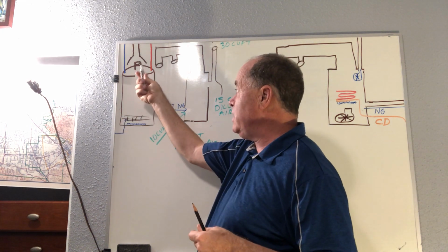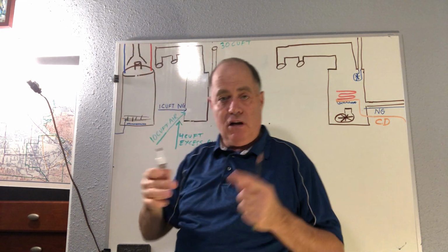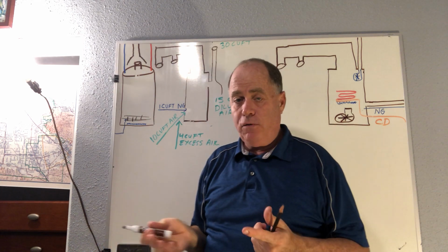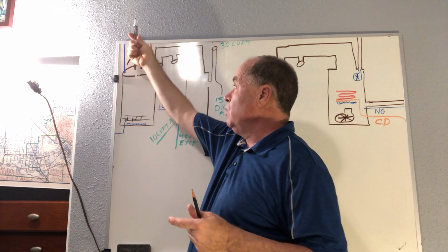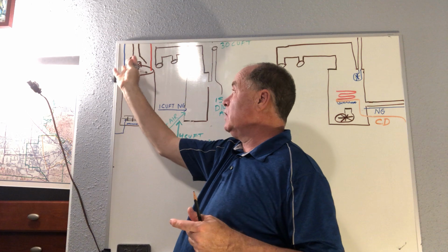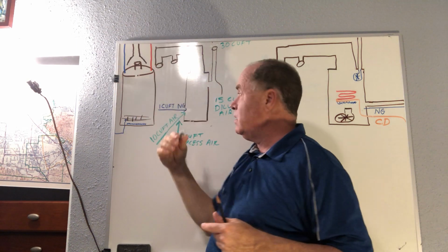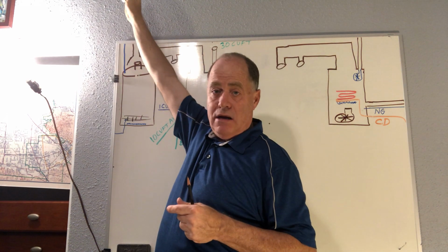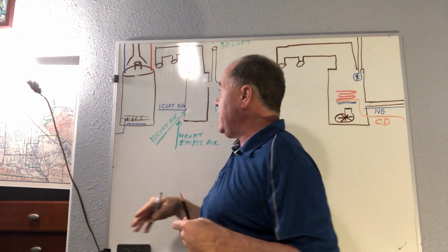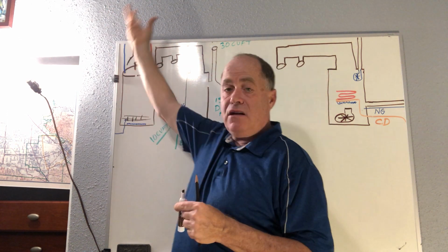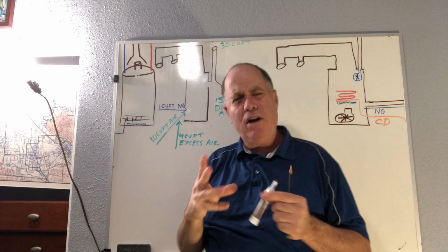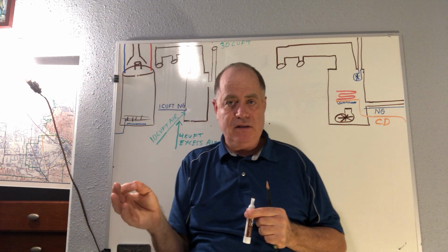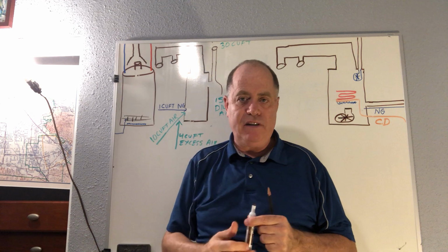Now the draft hood, once you get heat going up there, and a lot of times it may take a good 45 seconds or so, the warm products of combustion are lighter and they rise up, and it draws extra air in this way and moves the products of combustion along. Now, one of the main byproducts of combustion is water vapor.